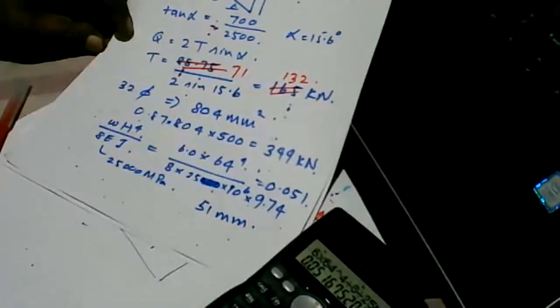So although we get additional tension, still the resultant tensile stresses or the minimum compressive stresses are better than the earlier case. And when it comes to the maximum compression, there's a reduction in the maximum compression as well.